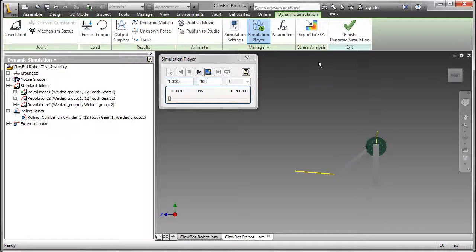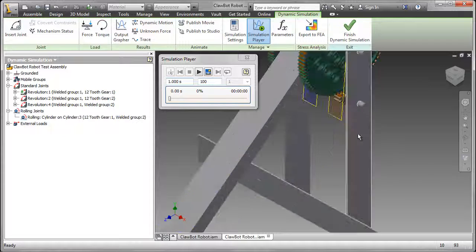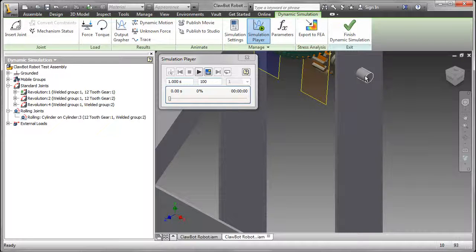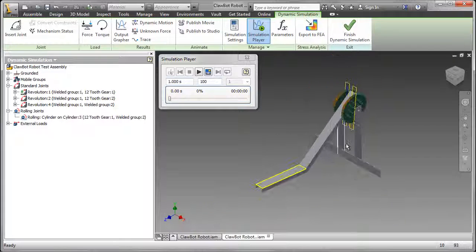You can also go to what we call finite element analysis and check whether or not the shaft is capable of handling the loads. So you select the time where the maximum load occurs and check the finite element analysis or stress analysis for that piece of material.